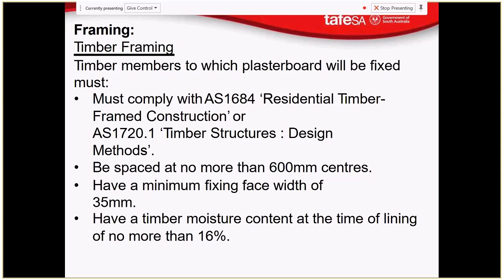But particularly with pine, we can kiln dry that, and we can get the moisture content down to about 10%, and then it leaves the timber shop at 10%. So when we're talking about 16%, that's just a little bit more moisture than the dry, seasoned timber that you would buy from the manufacturer or supplier.